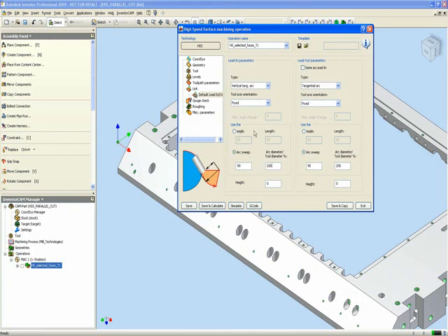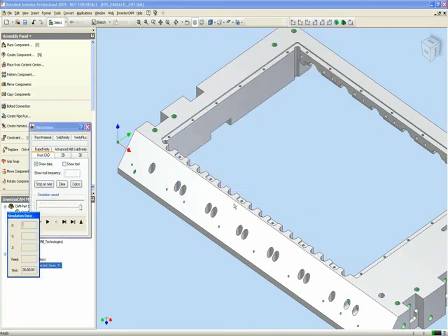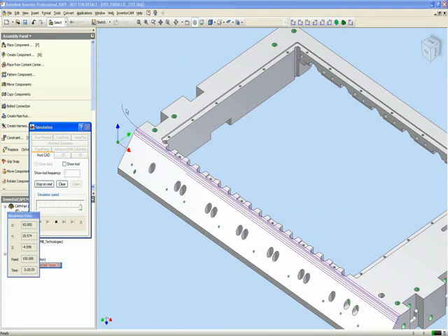We can also decide to use width and length instead, where I can say I want my width from the part as shown over here at 20, but my length only at 10. Now if I do save and calculate, and let me just change this back to same as lead in, you'll note that there is a change in the shape of my lead in. You'll note that it came from 20 millimeters out. However, we have a shorter arc from the bottom in, as shown over here.